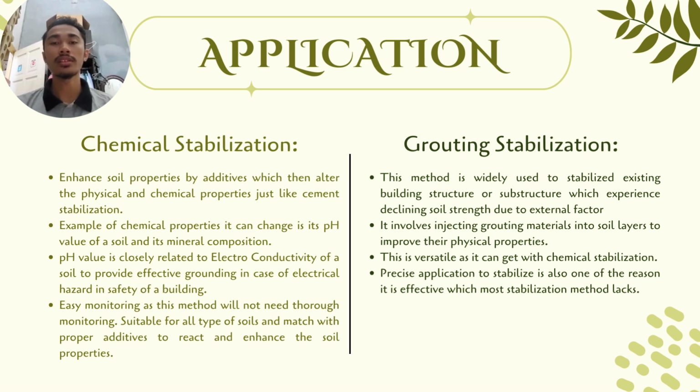Another method is grouting stabilization. This method is widely used to stabilize existing building structures, or structures which experience declining soil strength due to external factors. For example, there are limestones that have been eroded over years underneath a foundation. So in order to fill that void, we can use grouting stabilization to inject grout materials into the voids that are present at the moment. It involves injecting grouting materials into soil layers to improve their physical properties, just as I said just now.